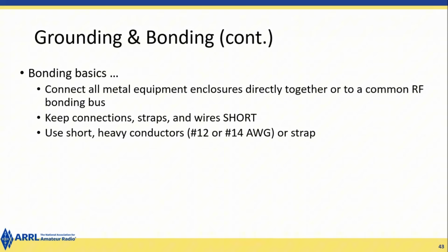So radio frequency interference, RFI. What are some symptoms? It varies. Interference consists of on-off buzzes or humming or clicks, if you hear that when you're operating CW or FM or data. Equipment can have direct detection, called RF rectification, on a speaker or something. You're transmitting, but you're hearing a squawking out of a speaker in your room. That can happen. Single sideband voice, similar to AM, sounds garbled or distorted.